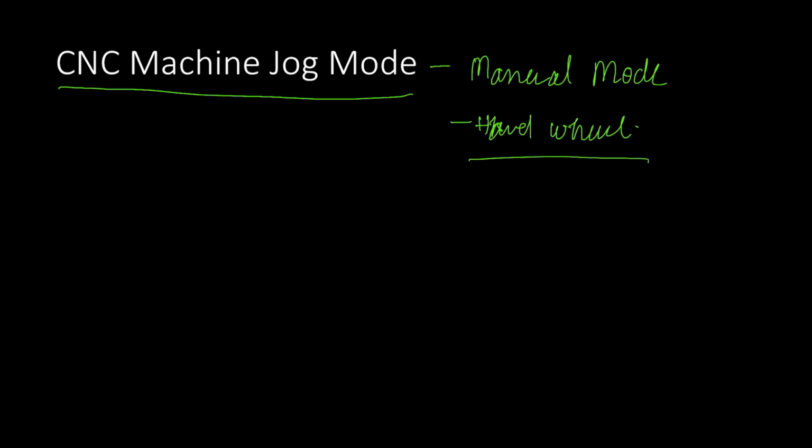You have to decide at which axis you are going to supply the pulse train, using the joystick, the manual hard buttons, or the turn wheel. Note that those things that cannot be done in manual mode must be done in manual data input mode, the second mode of operation.